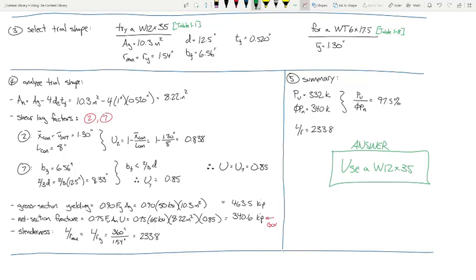A good example is if you have really big bolts going through really small material, then it could be inaccurate. So if our bolt sizes got pretty big, we might need to up our capacity a bit. With most tension member designs, you might have to iterate once, and that's it. If you're having to analyze 3, 4, 5, 6 members to get the right answer, you're probably doing something wrong. So you probably have an error in your calc somewhere.